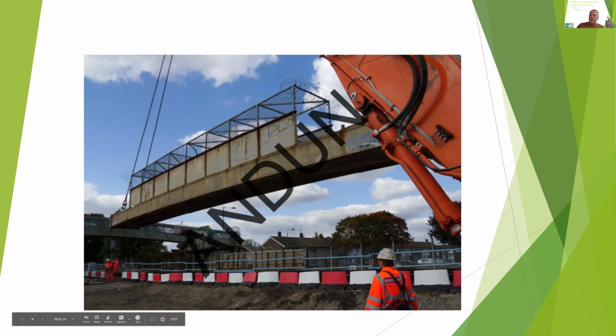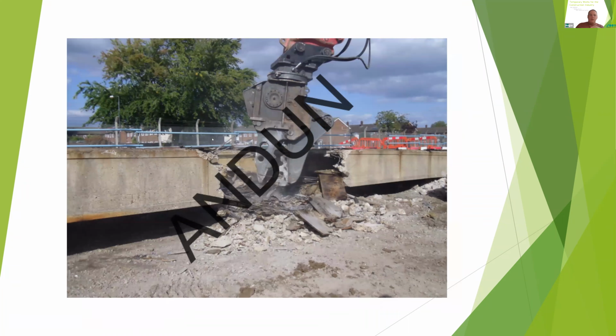You see we lifted it out, pretty much maintaining the original support conditions, lowered it to the ground, and then buried it at either end where the anchorages were, and then used a pulverizer to break out the concrete and release the stress in the tendons. So you can see it can be done safely. It just takes a little bit of thought.